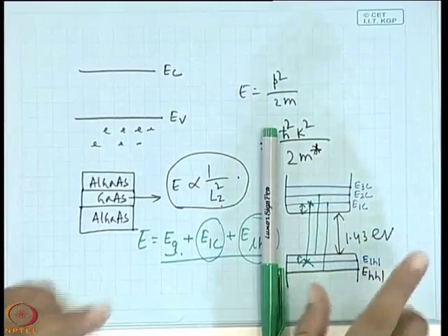So, that is the implication of the nanostructure. First you confine the carriers to a particular dimension, then its energy band will split, and you can expect more energy involved in the structure, greater than its band gap, and you can tune those energies E1c or ELH etc. This depends only on the thickness of the material.